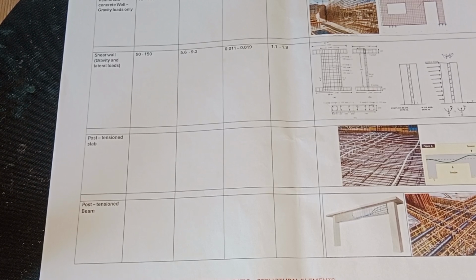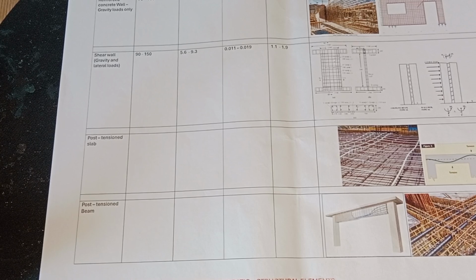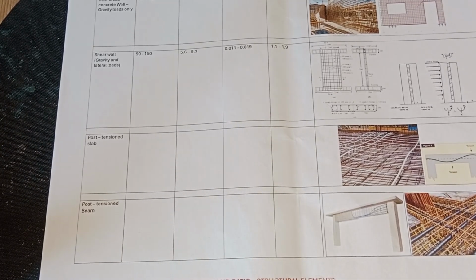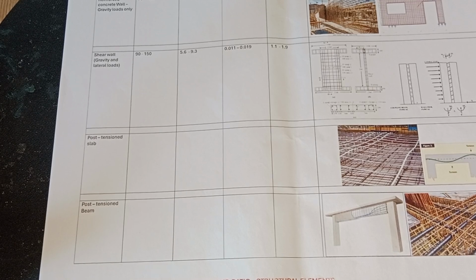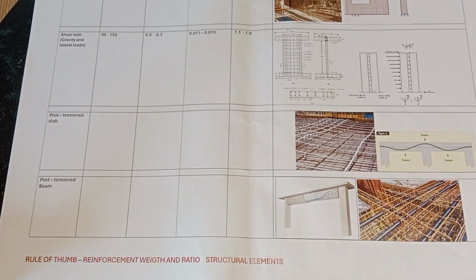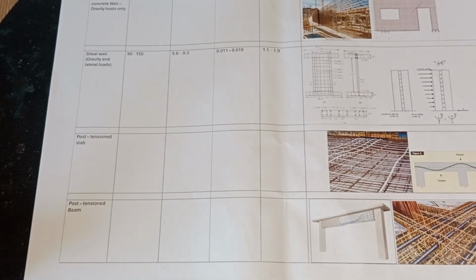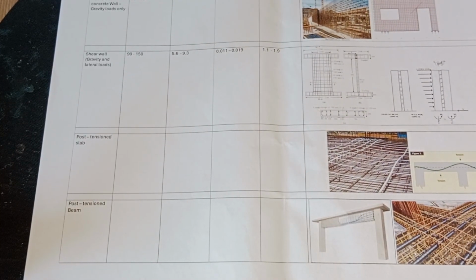For shrinkage, or for some cases, if you have grade 1, 2, 3 corrosive soils or aggressive soils, in these cases you may have aggressive conditions, and definitely you may have more reinforcement, and depending on other situations you may have more reinforcement. But these are just general rules of thumb that are helpful to understand what the optimized range is, and you can understand with the first check if it is wrong, if it is okay, or if it is under the limit.